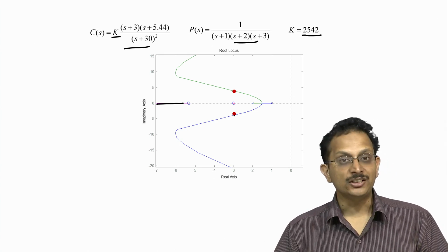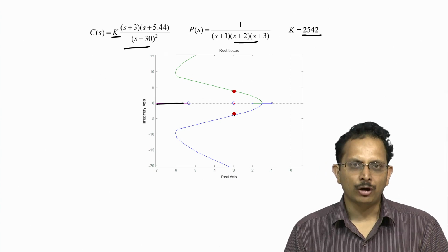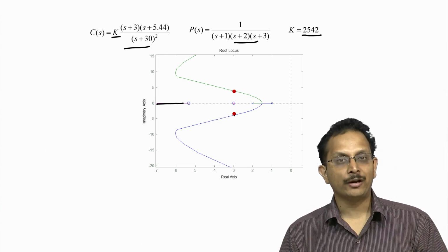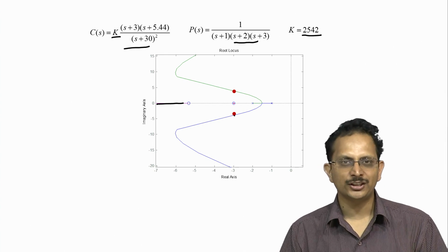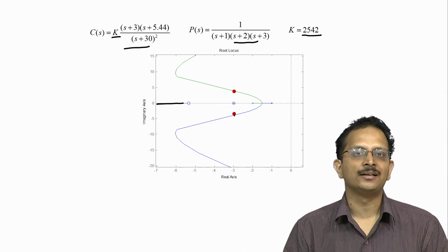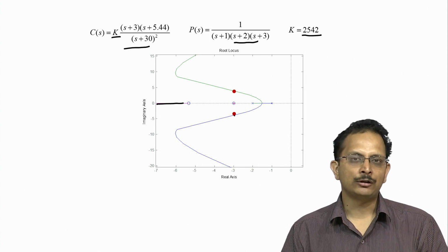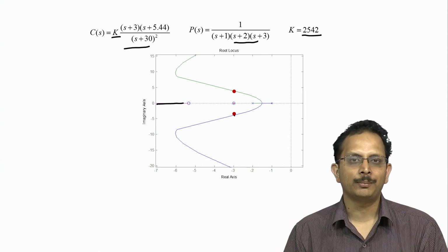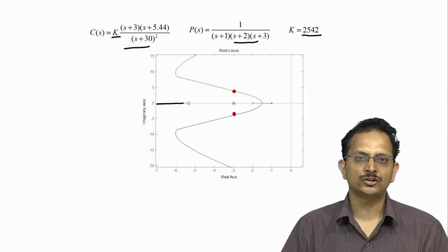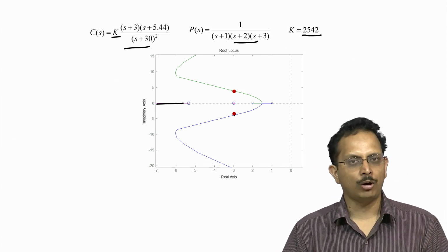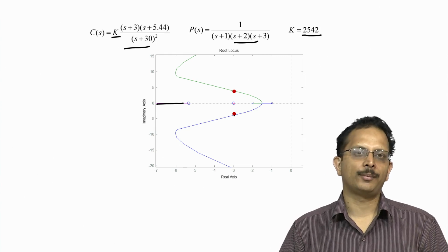That is not very easy to do in root locus, because unlike in Bode plots we cannot specify in a very transparent manner the performance specifications and the necessary gain that the controller needs to have in order for it to meet those particular performance requirements. Nevertheless, for simple cases it is possible to use root locus to also satisfy performance requirements.